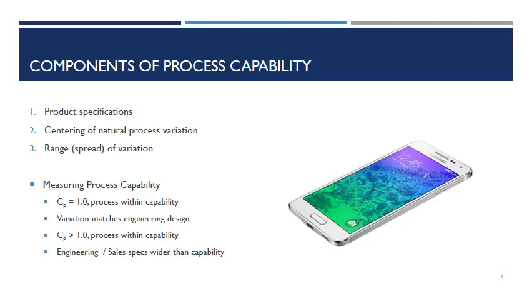A situation may occur in which the process cannot achieve statistical requirements. The process capability in this case would be less than 1, since the normal variation would fall outside the range of actual values. Such processes cannot be fixed simply by changing process variables. Instead, a fundamental change must be made to the engineering design of the system.